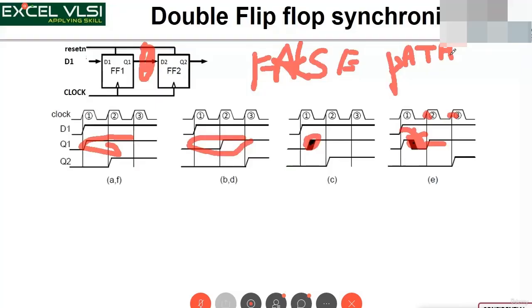So in fact, when we are doing gate level simulation also, we will ask the PD team to dump out all the synchronizer first flip-flop paths, write them out, and give them in a file.